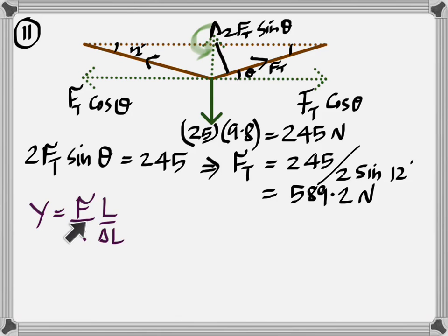So you get this. Now the Young's modulus would be given, although I did not mention it there. But then you got the force, which is the tension. So which means you have to find what this ratio is. So that's the plan. We just calculated the force. This is going to be given for aluminum. It is 70 GPa. And if we could get this, then we could surely calculate the area from which you could find the radius. So that's the next idea.